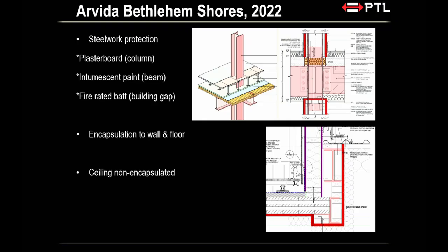You get that picture, right? And then the other thing we do is we make sure that there's a bit of overlap between all these fireproofing systems, right? So there's a bit of intumescent paint going above the batt, right? There's a bit of intumescent paint going below into the boxing of the column beneath the floor, right? So it's tricky, and we don't admit that this is the greatest, all right? But it is what we could do at best at the time, right? Probably 20 years from now, somebody will just say, why don't you just use that system, all right?